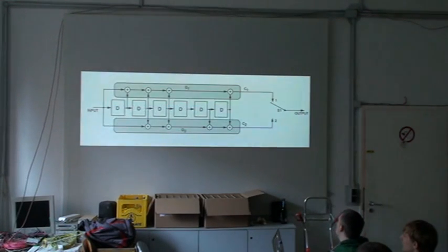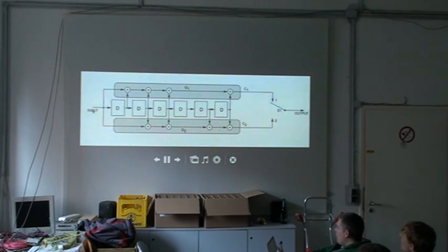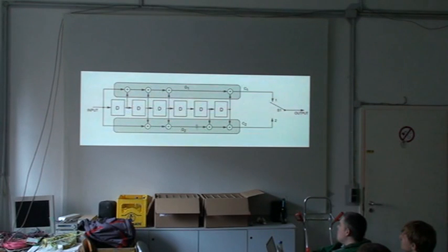Okay, next. The other part of GSM layer 1 that people usually don't understand is convolutional encoding. This is a convolutional encoder. What it does is it takes an input signal and runs it through a memory, a tapped delay line, a shift register. And then there are two output functions, each of which is a Galois polynomial based on the shift register content. This is an exclusive OR of a bunch of shift register states.